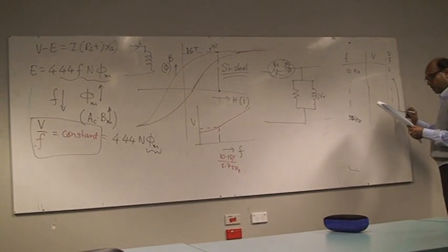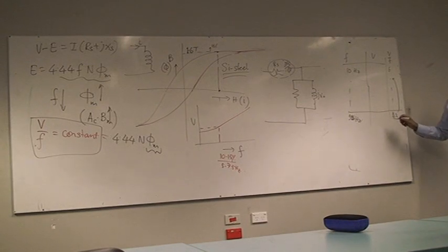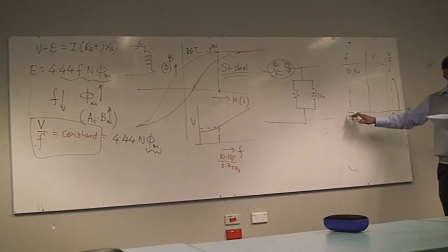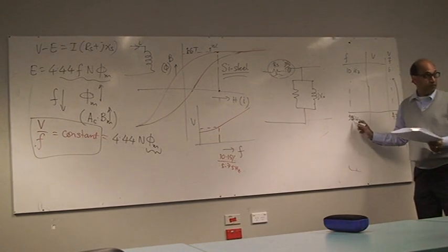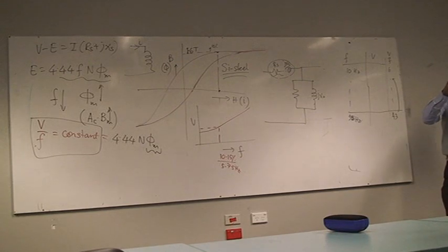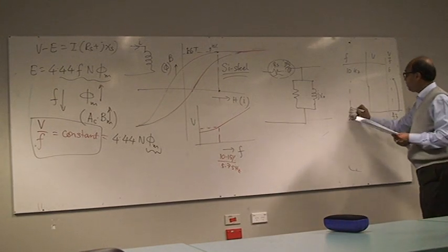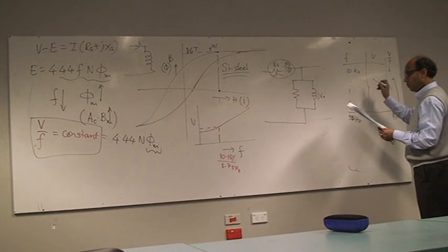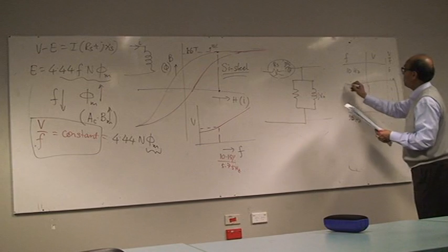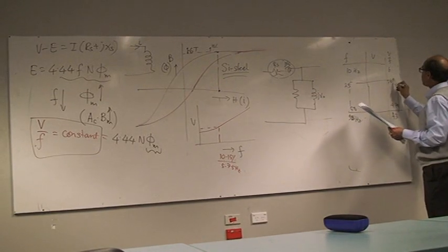So what you've got here, definitely this one is out of the way, because you are not supposed to give more than the rated voltage. When you go beyond 50, the motor clamps the voltage to the rated voltage, so that ratio will definitely be less because the voltage is less. But at 50 you got 4.76, and at 25 you got 5.08.